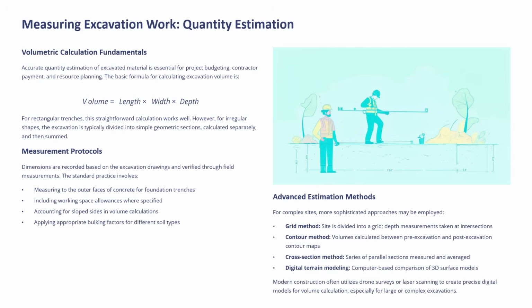Next is measuring excavation work, how the quantity of earthwork to be excavated in foundation is calculated. So basically we do volumetric calculations. In volumetric calculations you need three things: length, width and depth. Accurate quantity estimation of excavated material is essential for project budgeting, contractor payment, and resource planning.